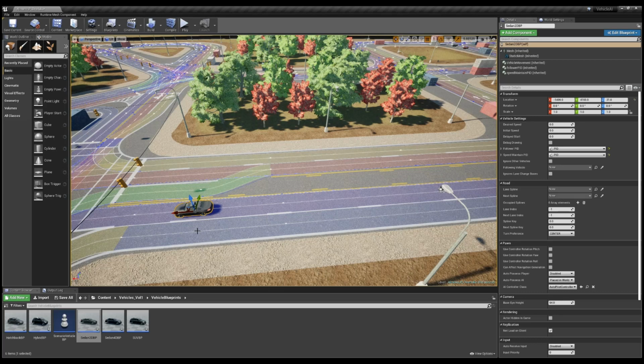So now one thing that we'd like to be able to do then is to set the speeds for the vehicles in our scenario. You can see over here in the details panel for our currently selected vehicle, there's a number of settings. So in this case, we have this sedan here that we'd like to overtake some other vehicles in the scene. So let's start by giving it a desired speed. So in this case, 35 miles per hour. And we'll have it so that it starts off moving at 35 miles per hour down this little stretch of freeway. And it's essentially as easy as that. Once the scenario starts to play out, this vehicle will be driving at 35 miles per hour down this lane. And it'll continue to drive and control at that speed and maintain its lane as long as the simulation runs.